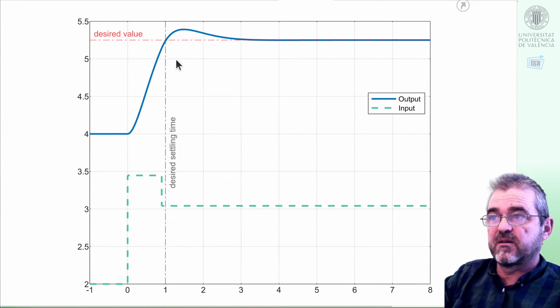The earlier I switch, the lower the overshoot, but the greater the error, in the sense that I won't reach the target value in the target time. So it's up to you to fine-tune this if you are happy with this strategy. Of course, there is a more complex strategy with a 3-step approach in which you can sort of brake in order to modify these shapes.